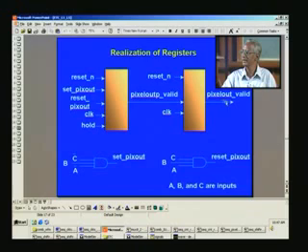How is it generated? In fact, this generation is already done here at this specific edge of the clock. That is one clock prior, beforehand it completes. So I just want to delay that computed value by one clock pulse, and therefore I put one more register. That's what I had explained earlier.